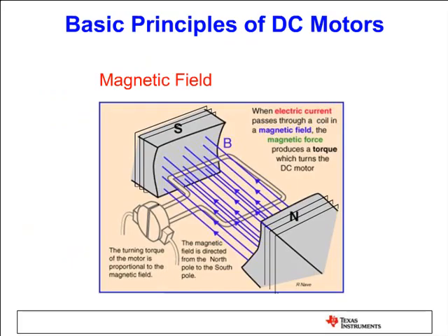In this slide, what you see is the very basic picture of a DC motor. Now, in a DC motor, there are a few alternatives. You can create the stator field using magnets, or you can create the field using windings, as shown in the figure. So the field vectors, the blue field vectors, are kept constant during the operation.